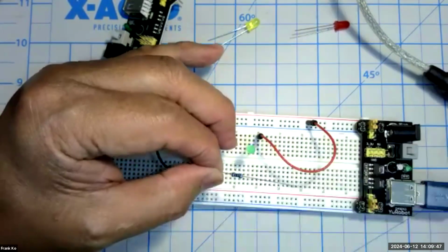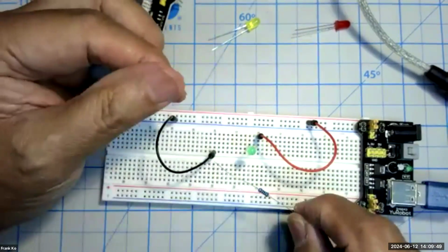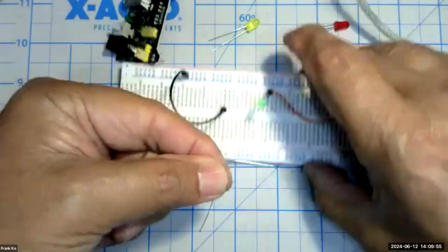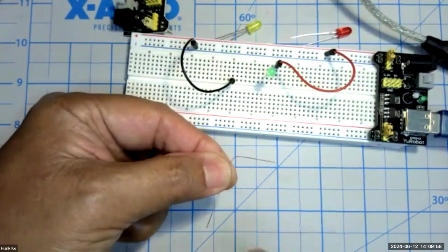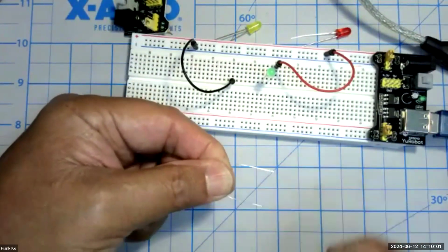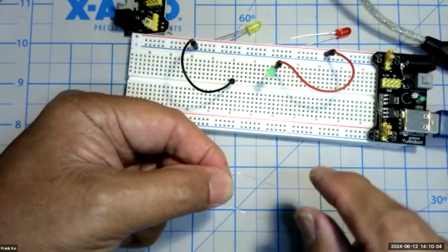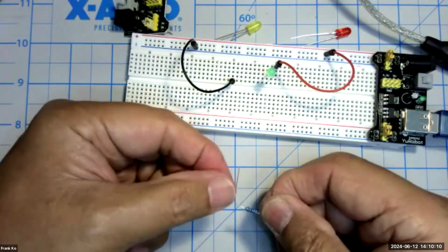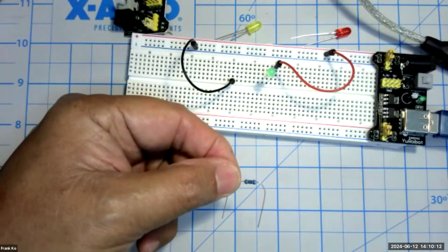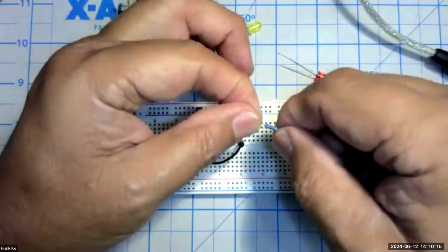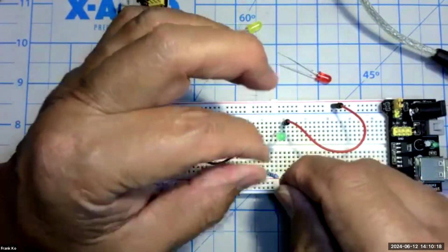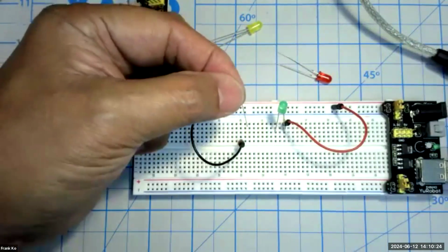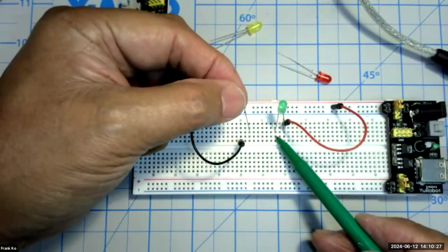So when we're going to put our resistors on the board, we're going to grab the resistor, give it a slight bend like so, and then a slight bend like so, okay? And therefore, we have created something that looks like the letter C, or the letter U, or the letter N, doesn't matter, just messing with you. Okay, so what we're going to do very carefully is grab one wire, the wire that we're going to insert, and move the LED out of the way. Our target is to hit 32D.